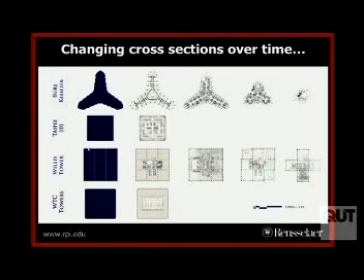Here we go. So if we look at plan form of structures, the World Trade Centers were square all the way up. So they were 7-to-1 rectangular cylinders, tubes. The Willis Tower, or the Sears Tower, is also square, but had a bundled tube arrangement where the tubes terminated at various levels. So you changed the profile of the structure. And that interfered with the flow around the structure in a manner that was helpful to avoid crosswind response. Taipei 101 has this sort of pagoda-type shape, so again playing with the profile. And Burj Khalifa is again a triangular structure, but also tapered, so it changes profile vertically all the way up.